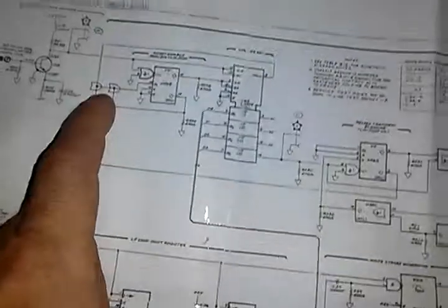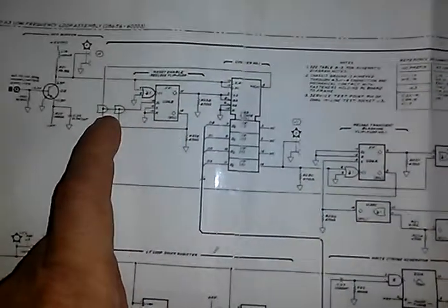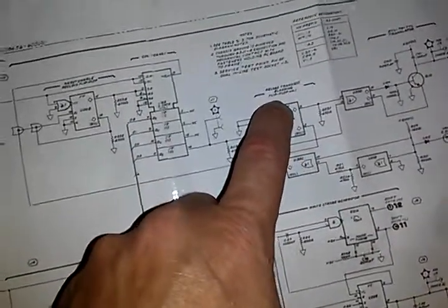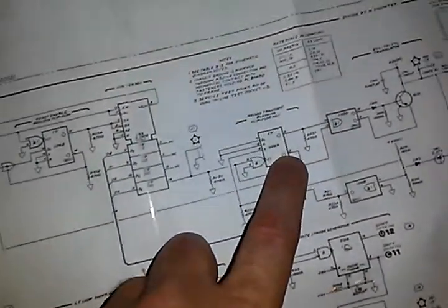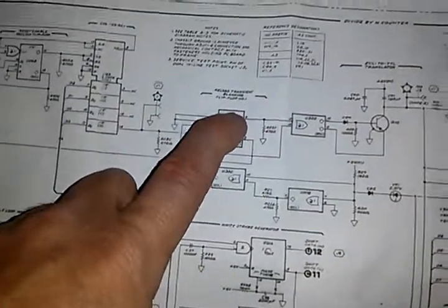Now, I didn't test this line because it was hard to isolate because it was ORed, not through a gate, but through basically traces being connected together. I checked this line, which is your non-inverting line. This is your inverting line on the latch. And this thing was dead. There was no activity at all.